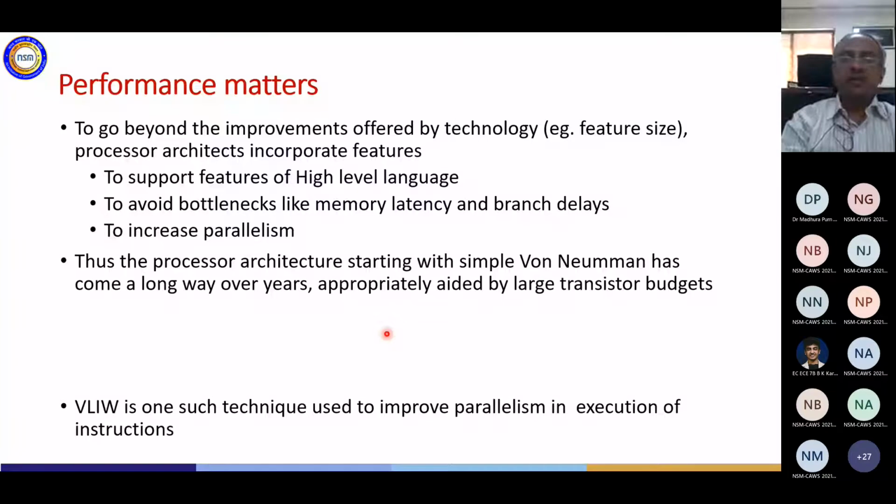So whenever such a branch occurs, the pipeline has to be flushed. And when the pipeline is flushed, at that time you lose work because it inserts bubbles in the pipeline. Possibly this was covered in the morning, and I'm sure branch prediction was told. I heard that. So to overcome branch delays, you use branch prediction.